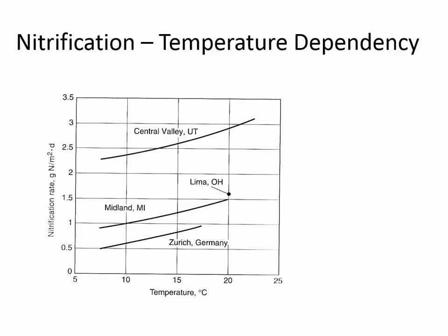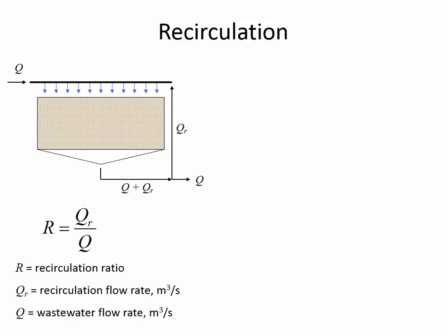And what this shows is that there's some temperature dependency, but to go from, at a typical 20 degrees Celsius, 3 grams per day of nitrate removal per square meter of surface area isn't so different than getting about 2.5 at 10 degrees Celsius. And so it's lower, but you still can get nitrate removal even in cold water.